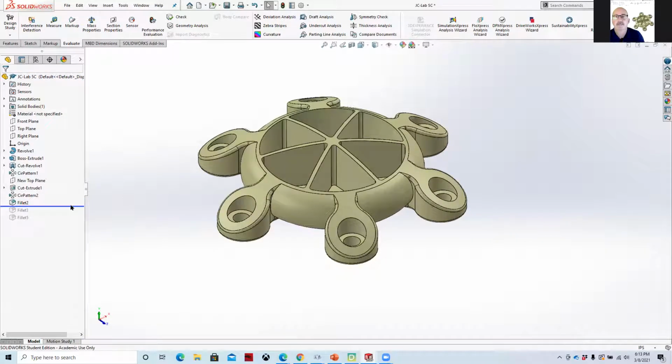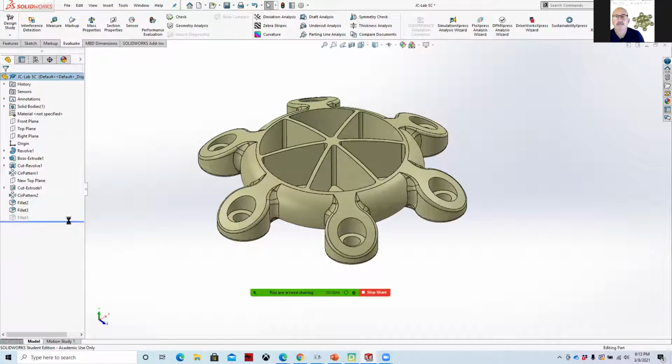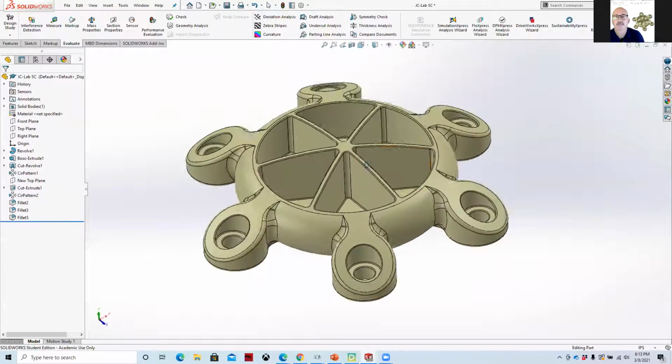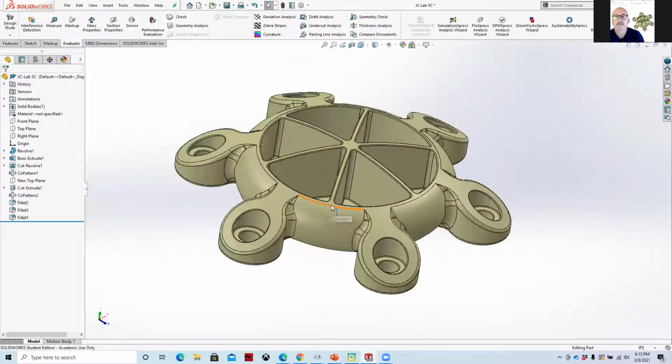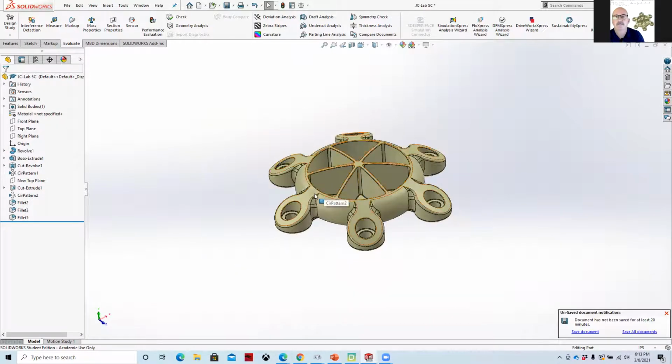And then we always fillet these things to make them better products. As far as the design aspect goes, you always want to put some radii on these, or you will have sharp edges. And that doesn't really work in the design field for most of your products. You can get cut on it. All right, and so that's our 4 projects that are due for lab number 5.